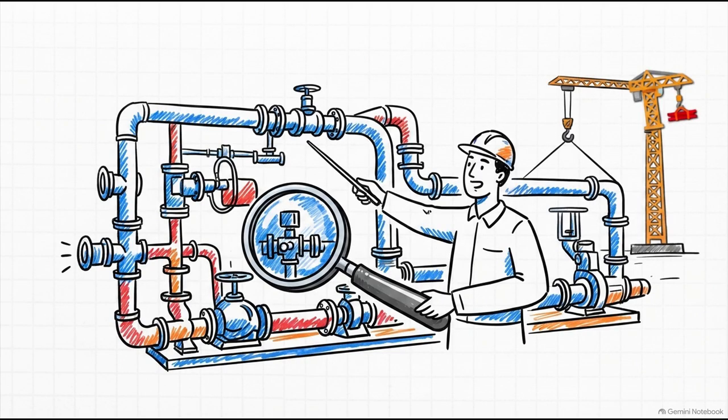If the shotcrete stream visibly changes on the wall, do not just stare at the nozzleman's technique. Check the whole system. Look at the mixture, the air pressure, the water flow, the hose diameter, the pump, and even the physical wear and tear on the nozzle itself. That entire chain dictates the quality of the final product.